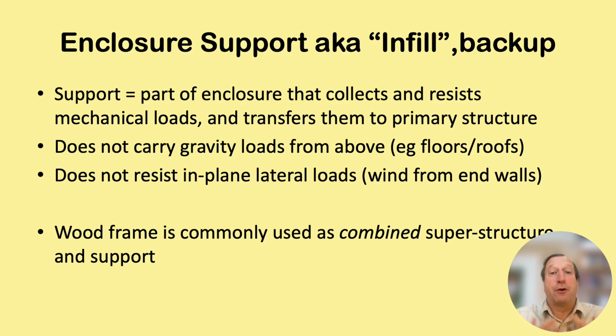So again, if there is a frame, if there is a superstructure like a limited amount of shear walls, then that is what the enclosure is transferring to the floors. The floors transfer to the shear walls, or they transfer to the braced frame or the moment frame. By definition, you're not going to have gravity loads like people stomping on floors transferred through the building enclosure. That is being collected by the superstructure.